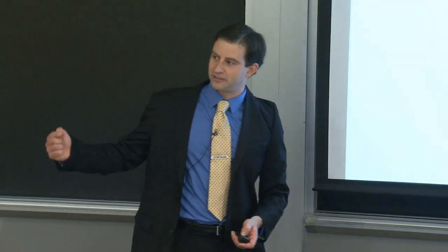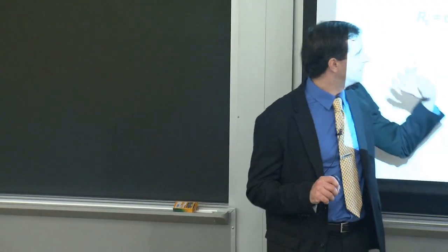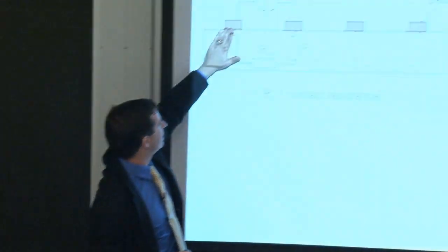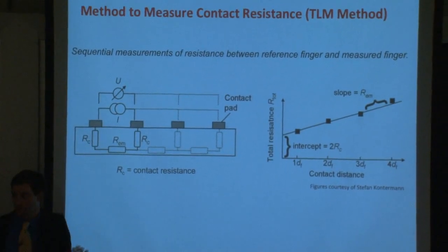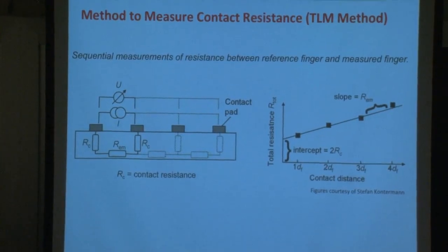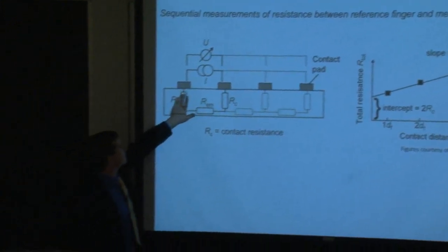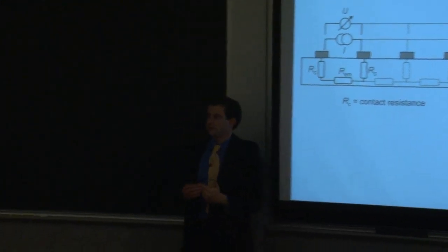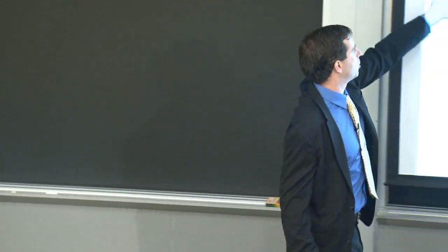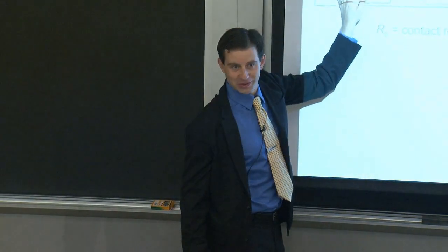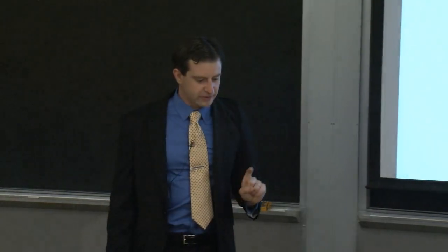And then there are line losses. So, let me back up one step. What can affect the contact resistance? Typically what affects contact resistance is the atomic interface between your metal and your semiconductor, whether it's an organic or an inorganic semiconductor. So the interface here is what determines the contact resistance typically. And of course, the dopant density within your semiconductor.